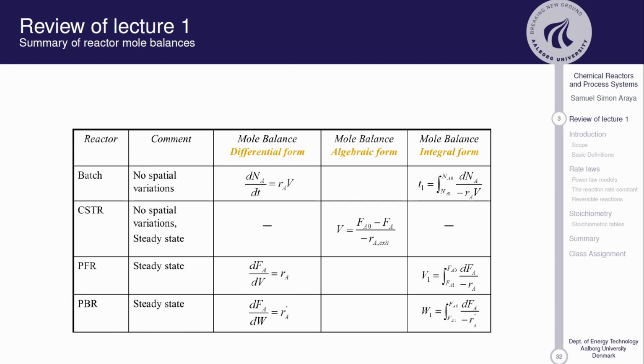And here are how the different mole balance equations were. First, just as a mole balance equation, how the moles into the system and out of the system, the accumulation and generation, relate to each other. We said that a batch reactor had a perfectly mixed situation where the concentrations are the same in the space, but we had a variation in time, so it was not a steady state reactor, and therefore our design parameter was time, and that's how we obtain our time.